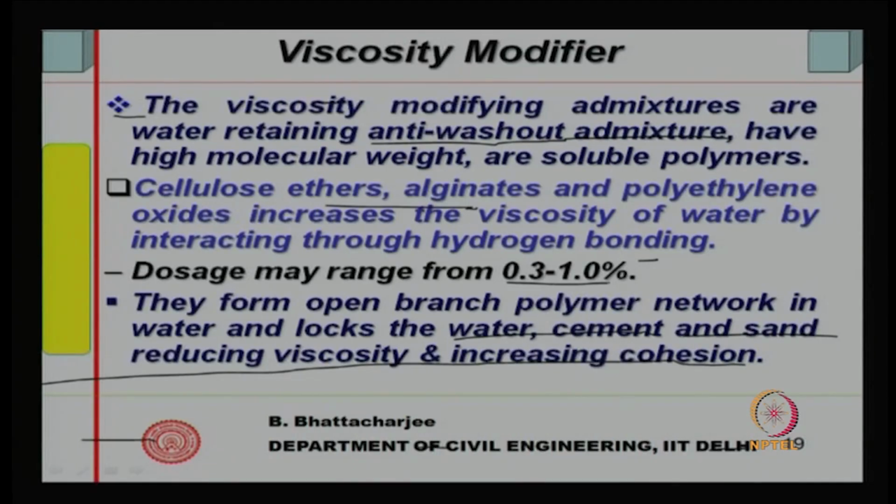Some of the self compacting concrete uses this material, because when you use polycarboxylate ether slightly in larger quantity, it has a tendency to bleed, as we said. But if it has a tendency to bleed, one way you can stop it is by using a lot of fine particles which can hold it together, very fine cementitious or inert material.